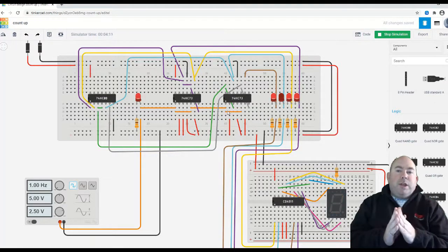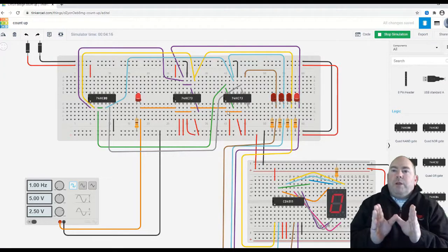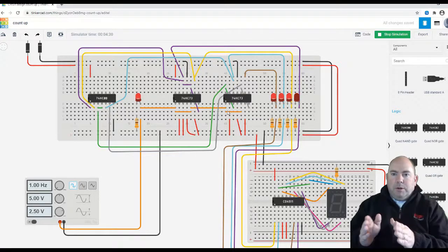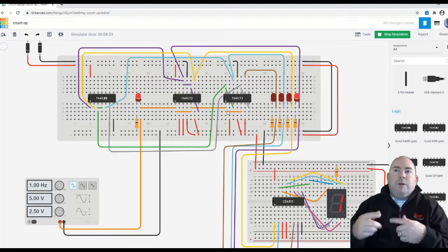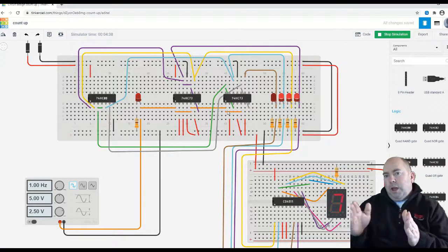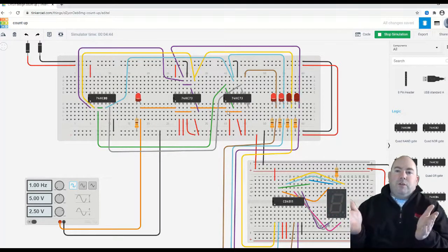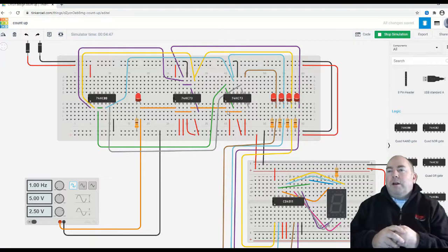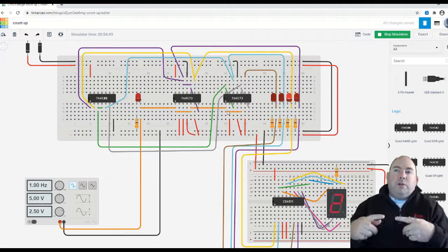Now, you don't notice that at all, but if you're trying to count fairly large numbers with this, that delay does build up with each bit that you add. So if you're trying to have a relatively large number with a lot of bits, that delay just keeps on building, building, building. If you're trying to count fast with a fairly rapid clock signal, the difference between getting that clock signal and your last bit actually registering that it has been clocked is a significant delay and affects your processing. So the parallel counter is better because all of your flip-flops are clocked at the same